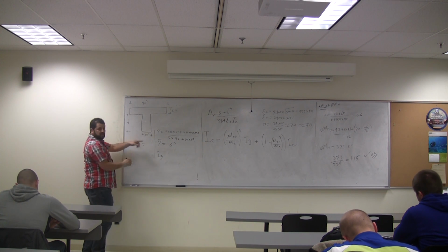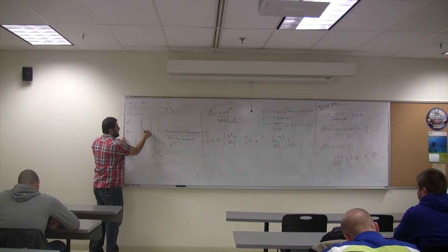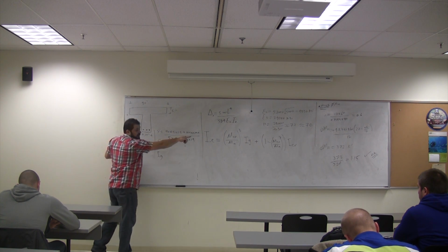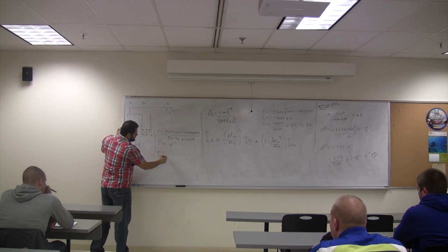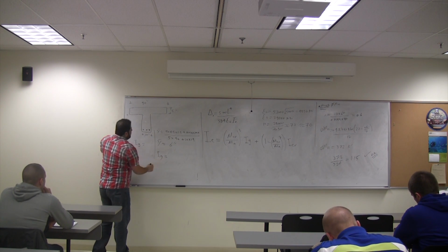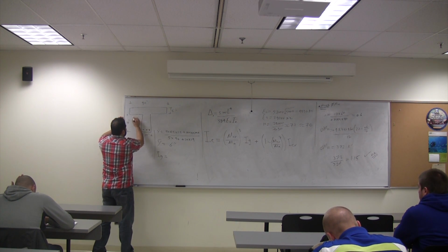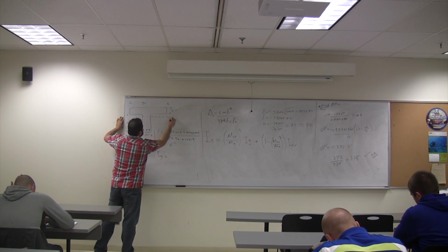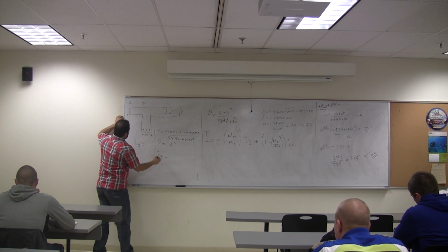Now, by the way, when I say Ig, steel is ignored. For Ig, steel is ignored in the formula. This is the ACI formula, by the way. So Ig, each component. So that's our y bar here, 6 inch.